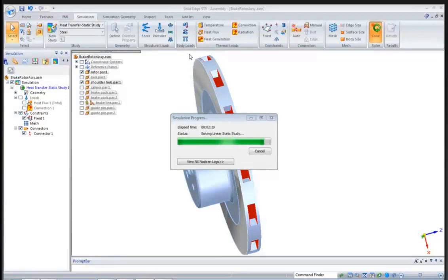So we can say with Newton's law of cooling that the temperature of this surface minus what they call T infinity, which is the temperature of the air way away from that surface, times a certain constant is equal to the heat flux. That certain constant is called the convection coefficient. The convection coefficient is not as easy to just look up. It's dependent on this material, but it's also dependent on whatever fluid you have, and it's also dependent on the geometry. So you're going to have to spend a little more time researching what convection coefficient you want to use.